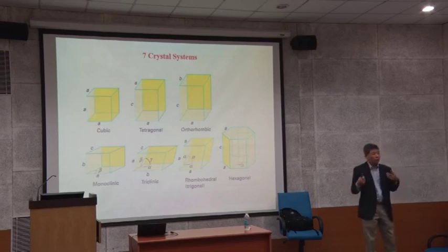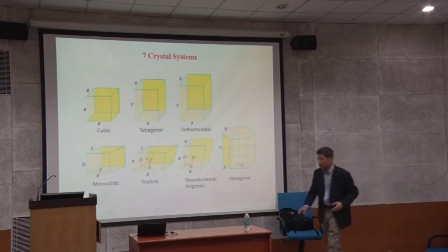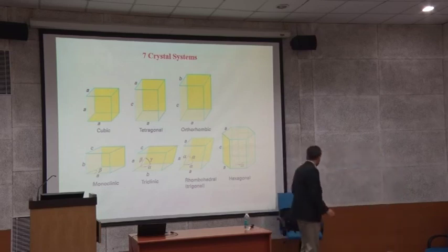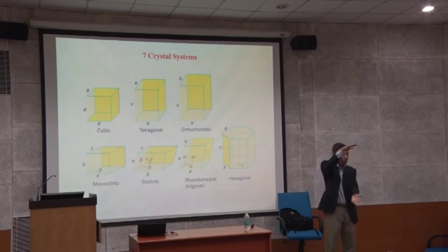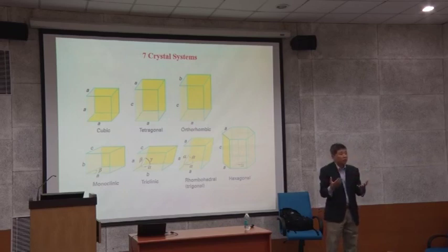This is a (100), (010), (001) plane. All three are different planes. For example, you have a cubic lattice, something like this, and this, all equivalent. So that means they contribute to a single peak in the cubic system. But if you have it stretched this way, this one and that one are the same, but this one is different. So the different one gives a different value of X-ray diffraction peak.